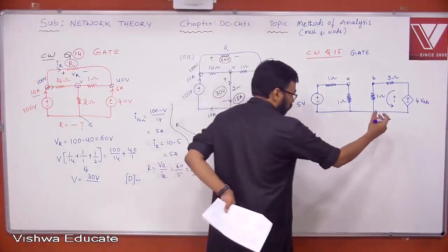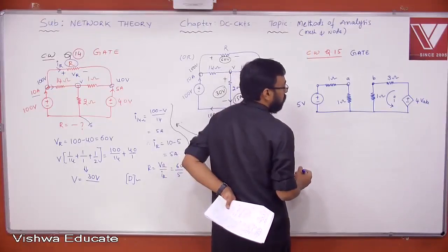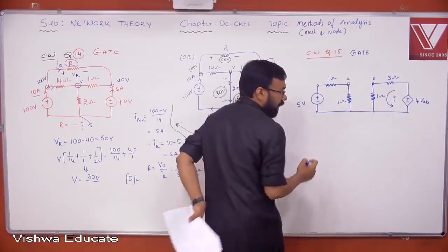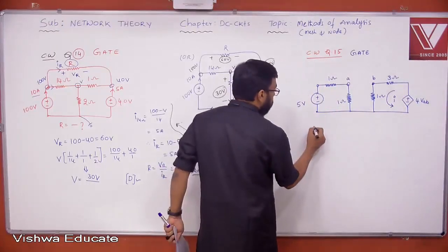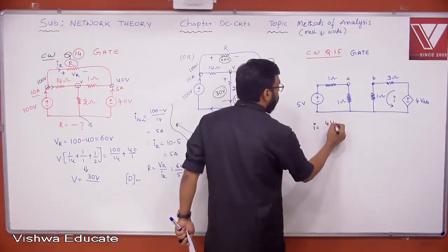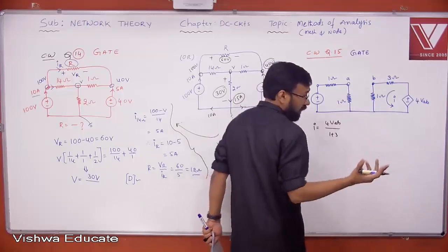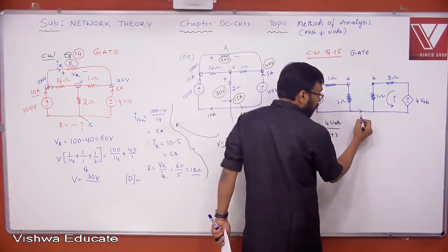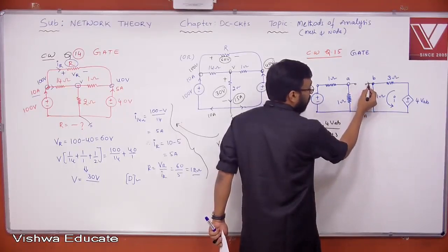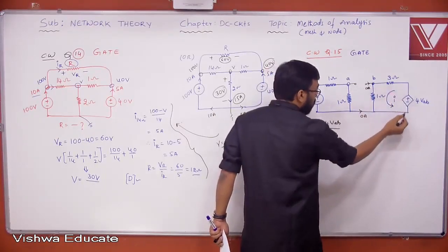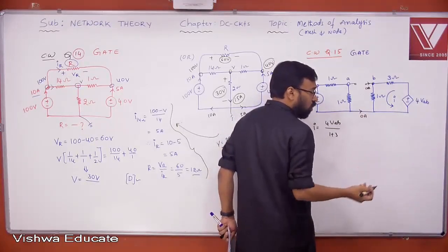Let us look at the dependent source problem. Okay. Now, what do you get here? I is equal to, you can write directly I is equal to, let me change the pen. Okay, I is equal to, what is I? 4 VAB by, yes or no? 1 plus 3. Okay, these two are independent loops, yes or no? Can you expect any current here? No current is passing here because there is no return path. What is the current here? 0 ampere. Then what is the current that should come here? Also 0. Either direction doesn't matter.